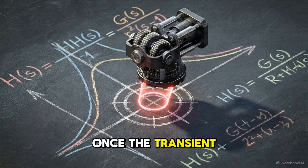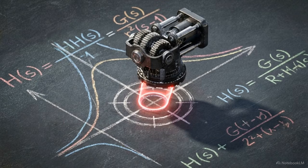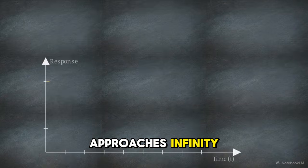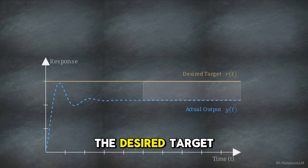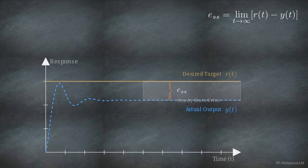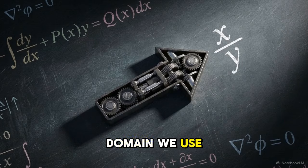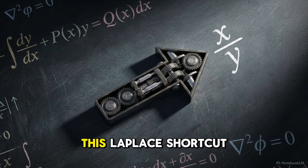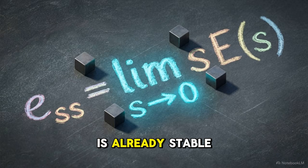Once the transient effects decay, we evaluate the system's final operating condition, the steady-state error. Evaluated as time approaches infinity, steady-state error calculates the permanent numerical difference between the desired target input and the actual output the machine achieved. Rather than solving complex differential equations in the time domain, we use the final value theorem. This Laplace shortcut lets us compute the steady-state error directly from the frequency domain, provided the system is already stable.